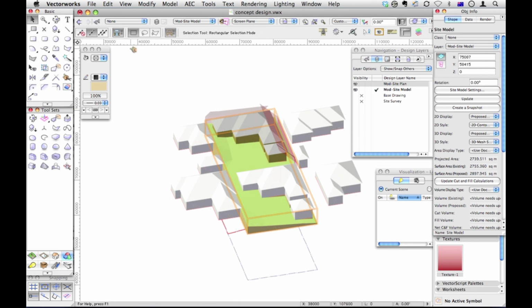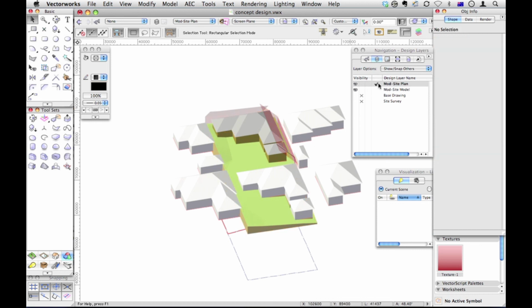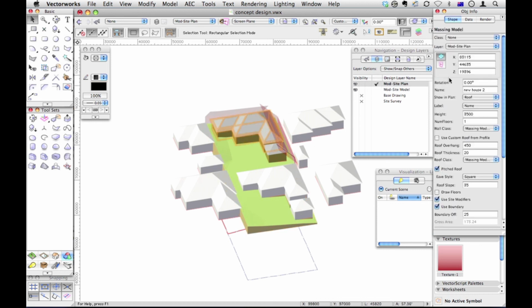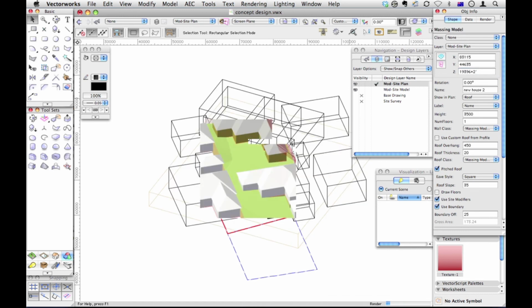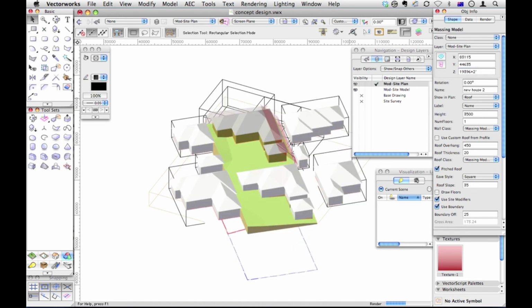So this would give us the opportunity to play with the height of this object. So we could take this house and say, well, actually, because of the site sloping up, I've actually got to lift that object. I need to go back to this layer here. So that house there, I might need to lift that up by a couple of feet in order to avoid some landscaping problems around there. If I lift that up by 2 feet, what does that do to my house in terms of the height to boundary restrictions?